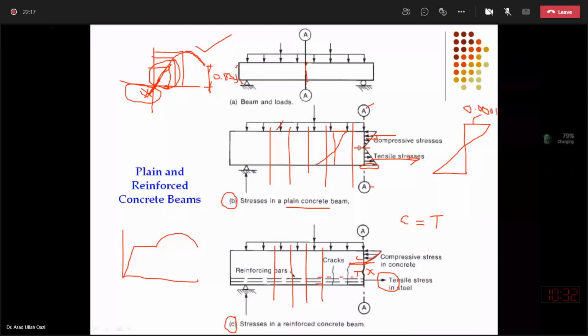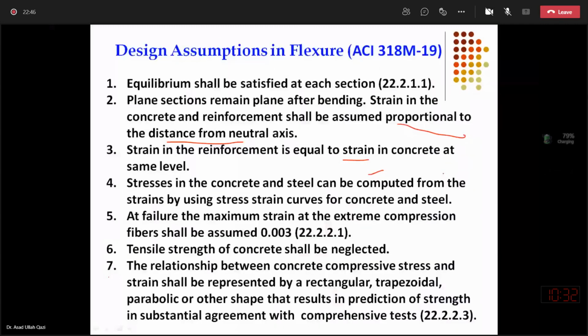If the steel over here has the strain 0.001, suppose, since I have the idea of stress strain of my steel bar, I will say this is the strain abscissa, and then corresponding to this, what is the ordinate, I will measure the stress. So I can draw from the strain diagram corresponding stress diagrams if I know the stress strain curves for the materials.